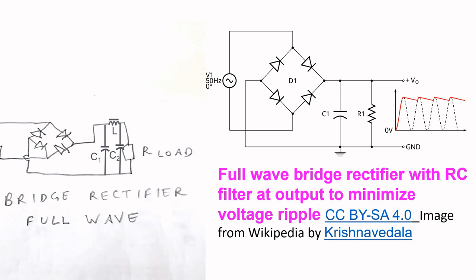The voltage drop across each silicon diode is about 0.7 volts and can be significant in low voltage rectifier applications, as the diode does not conduct when the voltage in the cycle is below 0.7 volts.